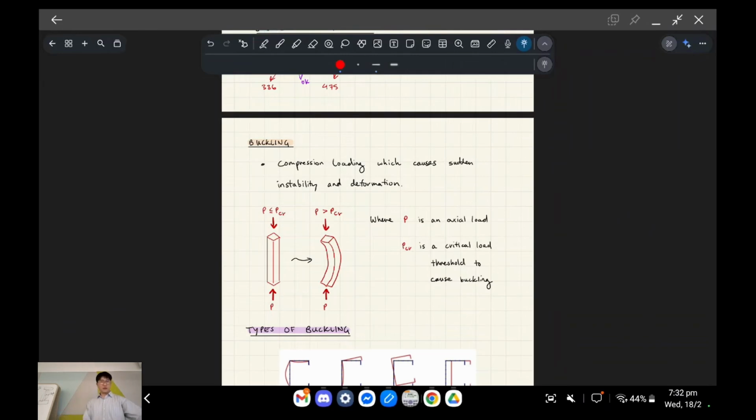If this was my water bottle, for example, if it was a much more, what's the other word? Stubby. If it's a much more stubby shape, so it's much thicker based on its length, and I'm pushing down on it, it's going to fail in a normal squash loading. There's not going to be any buckling, right? So this is based on the shape of objects. They're going to experience buckling in a different way. Does that make sense?